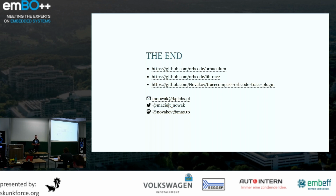Hello. So thank you for your talk. Very interesting to see more people interested in trace. I love that. With code instrumentation, you obviously add overhead because, as Nicholas showed yesterday, the ITM FIFO is strangely designed by ARM, and you will have some wait cycles potentially, and you wait for your trace to happen. The Orbuculum stuff also supports J-Link in one way or another. Do you know if they also support RTT as an I/O channel?